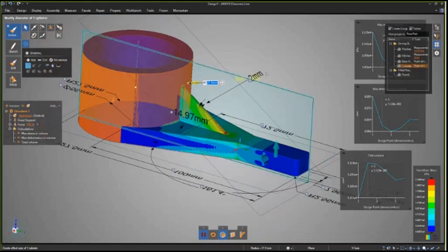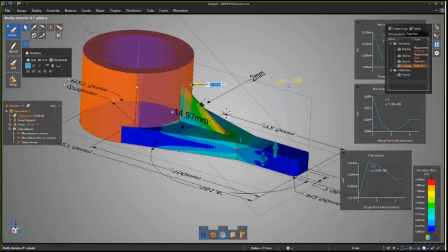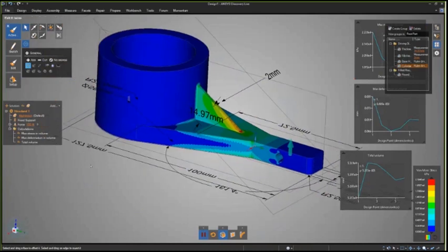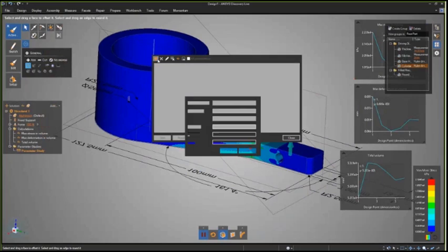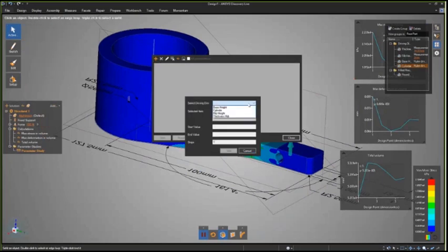So I've set up a few different parameters, things I want to study. I don't want to have to make a bunch of changes and follow these charts here. I want to gain a better understanding of how they all relate to each other. So in the recent release of Discovery Live, we have this new functionality for a parameter study. So I'm going to go ahead and turn that on, and it creates this window here. And we start by adding in the parameters that we want to study. So there was the thickness of the rib.